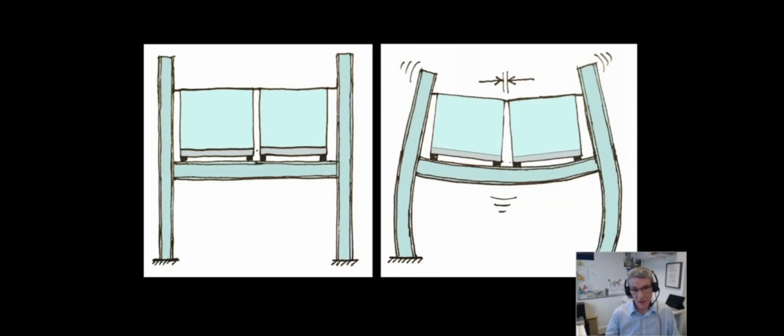When modules are placed on the supporting structure, the structure deflects and various forces arise in members and connections. As each level of modules are placed, the deflections increase. Finished and often decorated modules are placed, and if these movements cause stresses, then damages may occur to the finishes. In extreme cases, there could be preloading of the connections, so a staged analysis might be informative in this case.